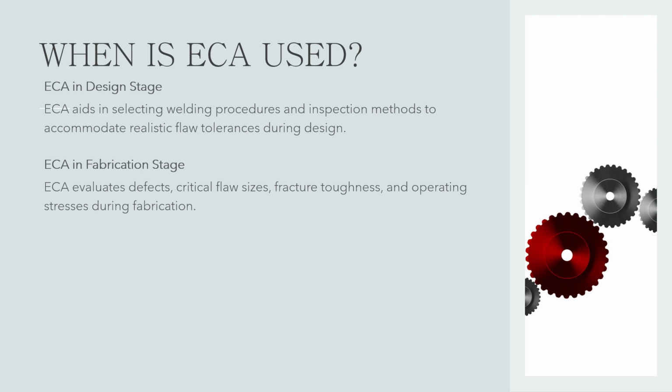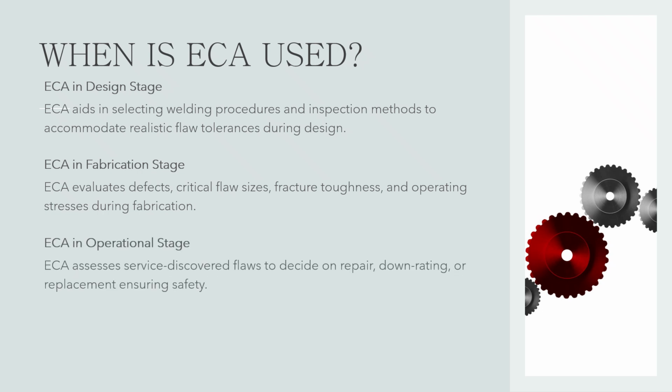maximum critical flaw sizes, and assesses minimum fracture toughness or maximum operating stresses. During operation, ECA becomes crucial for assessing flaws discovered in service. It helps decide whether these flaws can safely remain in place or if repair, downrating, or replacement is necessary.